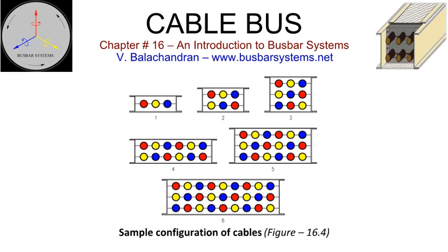Cable joint and terminating kits. Cable joint and terminating kits are usually purchased items and include 2-hole type cable lugs, earthing lugs, stress reduction cones, heat shrinkable sleeves, and high tensile steel galvanized or silicon bronze fasteners. Adapter plates on the equipment shall have a drilling pattern to suit the cable lugs supplied by the cable bus manufacturer. Ground conductor. In most installations, aluminium enclosure acts as a ground conductor.